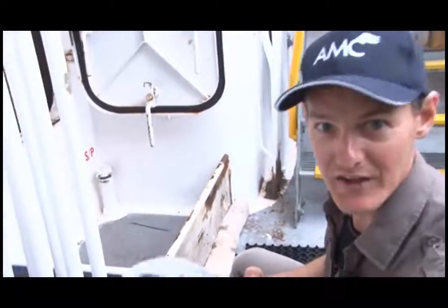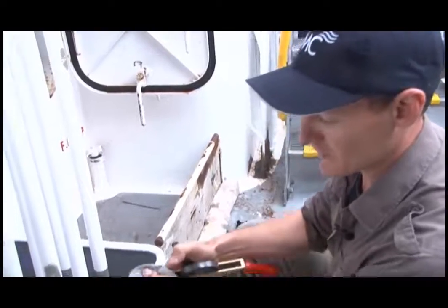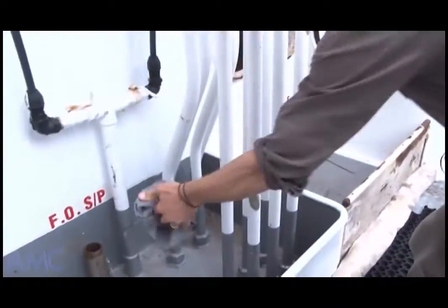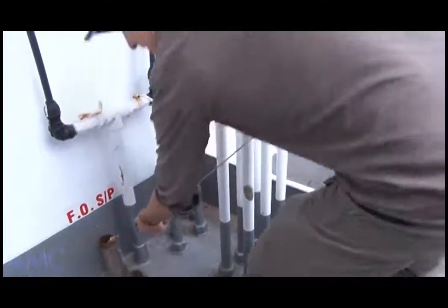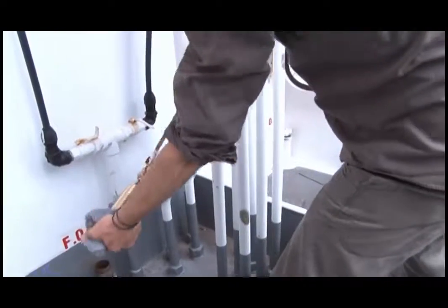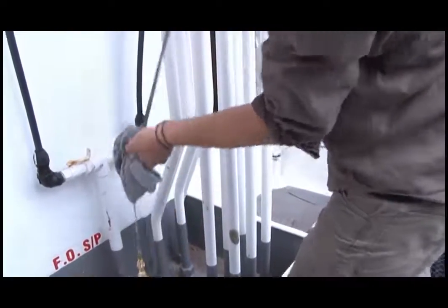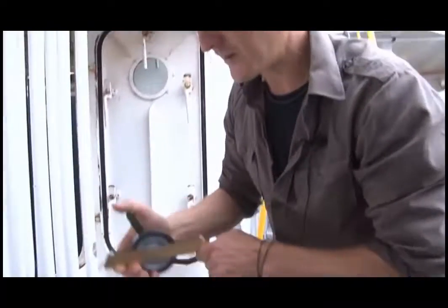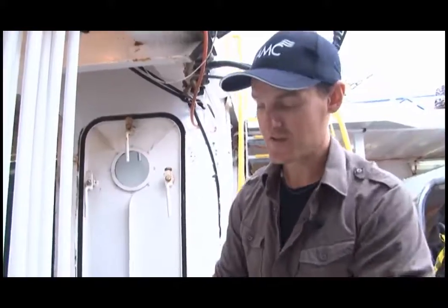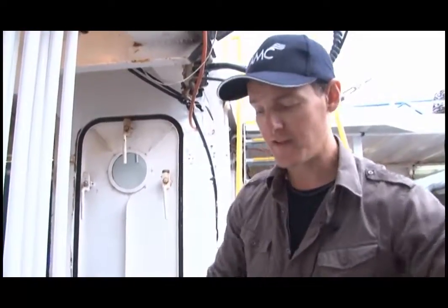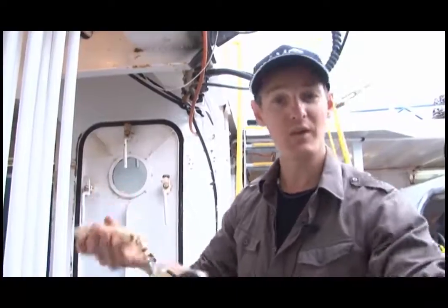But it's important at this stage that I have a handy rag, and what I'm going to do is wipe a section of tape. I'm going to reel it in and then wipe the next section of tape, wipe the weight, because what happens is if I wind it and I've still got diesel fuel on it, it's going to wind up into the tape, the whole thing will get wet and it'll be impossible to read. I'll have to string it all out and wipe it nice and dry. So that's the procedure. We'll work out from there the level that's on the tape. We can work out how much quantity of fuel that we have in the tank itself.